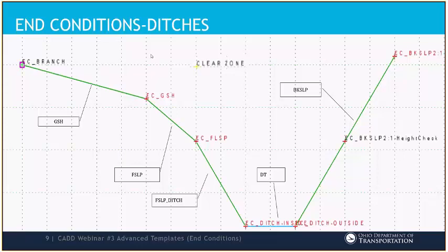For the situations where you only need two slopes, this point just moves to be right on top of the grade shoulder point. That way it's still there so that it will connect to the right pieces if you ever switch to needing that down the line. All you do is move this point to here. You'll see two points on top of each other sometimes, and that's okay.